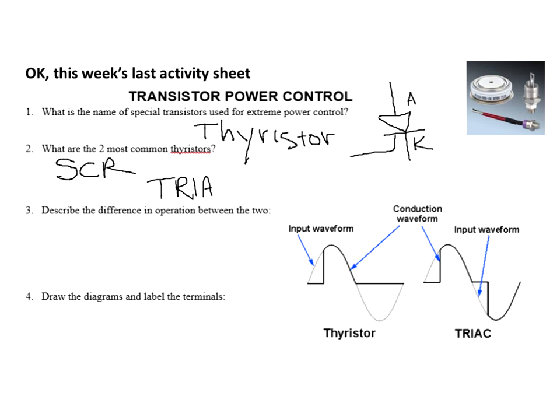Let me tell you where these names come from. SCR: a rectifier right here, and it's controlled right here. A silicon rectifier and it's controlled. That's what it means. I don't know if you caught that, but there you got it. A rectifier that's made out of silicon, 0.7 volt drop, but you can control it. A silicon controlled rectifier.